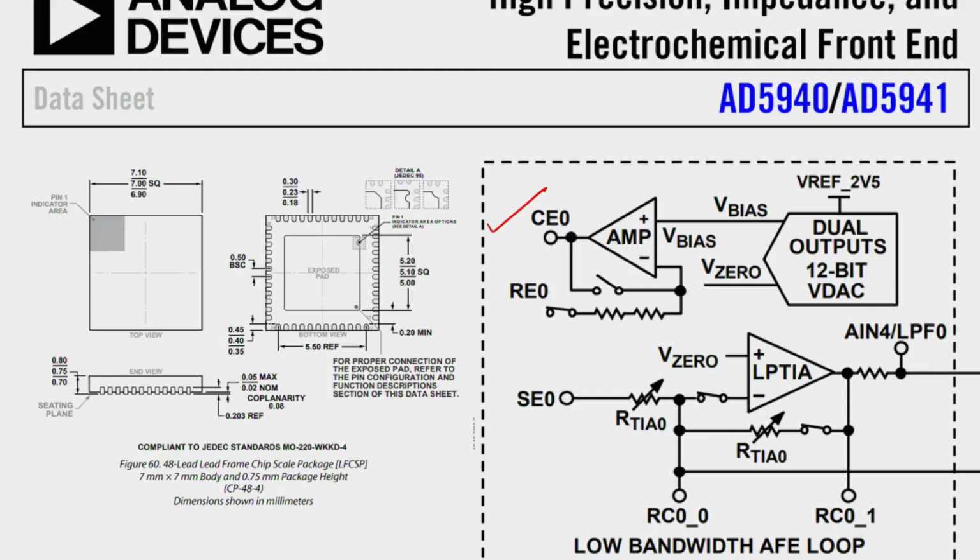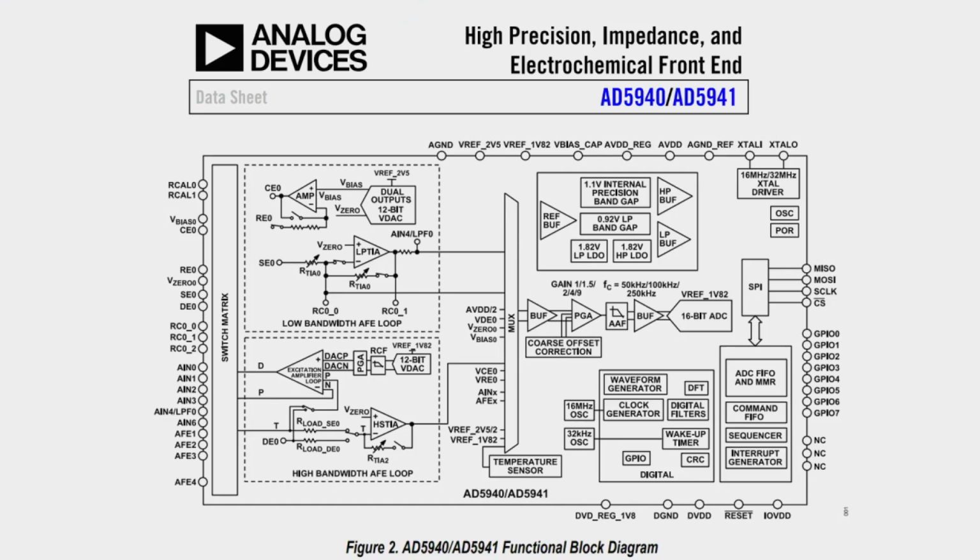Another query regarding this chip you told, something totally new for me at least. Because we have a big potentiostat, my question here is, can you use it for voltammetry? Yes, you can change the potential with time, so you can use it for voltammetry also. They have this functionality here. This waveform generator you can use for voltammetry also. Let's say you want a triangular waveform for voltammetry, so you can program that. Oh, okay.